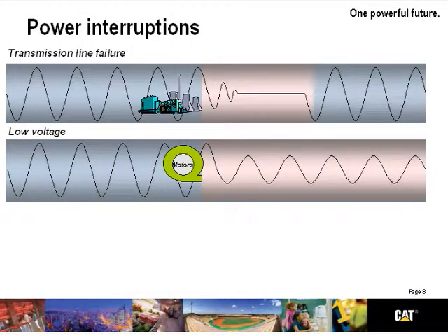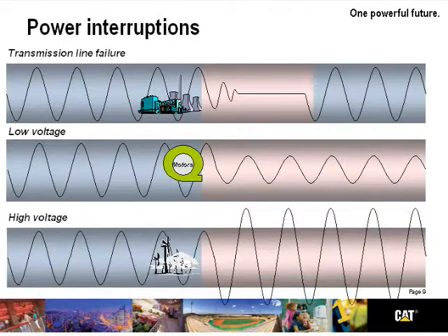Next, we talk about motors being introduced. And many facilities have motors that come on almost randomly throughout the building because of different manufacturing processes. When those motors come on, they absorb a great deal of current. As a result, we see a low voltage situation. Low voltage often manifests itself in the ways of, well, when the lights go kind of dim during the day. Typically, that means that something else is drinking up that voltage.